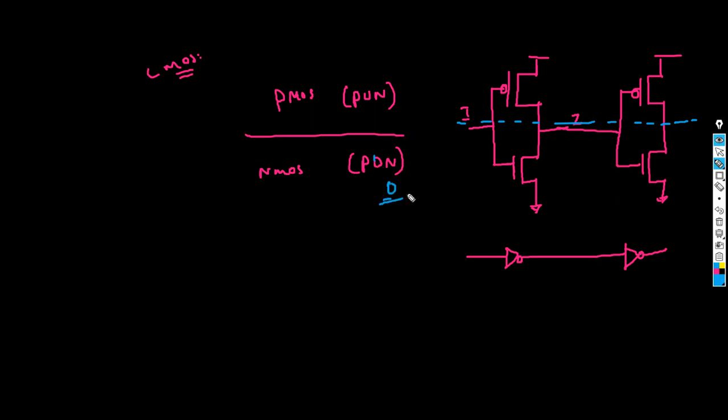Okay, so that is the main reason we prefer CMOS, because it is giving you both strong one and strong zero, and we don't see any kind of weak values, and it is easy to implement when it comes to overall circuit design and implementation. Okay, all right. So moving on to the power dissipation.